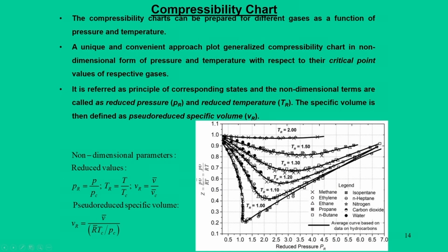The entire idea of representing this graphical method in a non-dimensional form is the principle of corresponding states. If I plot Z versus pressure, as was shown graphically, it is true for one particular gas, and we call it a compressibility chart for that gas. Now we are going to frame a generalized compressibility chart which is true for all gases.